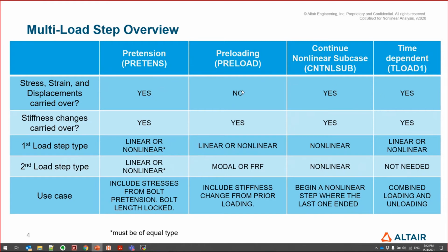So be careful with that, PRETENS and PRELOAD. But in all cases, we carry over the stiffness. That means the effect of pretensioning is carried over, but the result due to pretensioning is not carried over when we use preload. Modal and frequency response, you can only do preload. But if it's linear or nonlinear, you can choose. You can choose to use PRETENS where we carry over the results, which is more accurate.